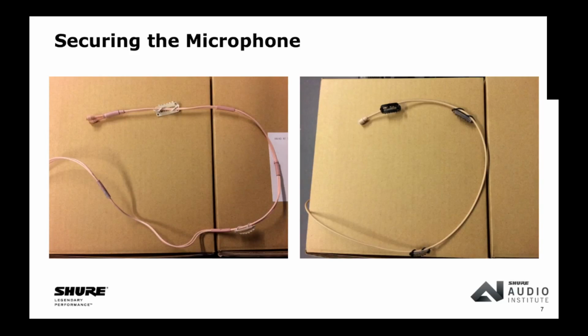And so if one of the elements, the primary element, goes down, the mix engineer can switch to the backup. So two packs both live? Both live, but you're only hearing one all the time. Yep. And do you put them close to each other, or do you separate them out? We try and separate them out on the belt a little bit, just because depending on frequency content, you can get intermod issues with the packs so close to each other. Okay. Cool. That's a good point. I didn't see that. One more thing on the taping too.